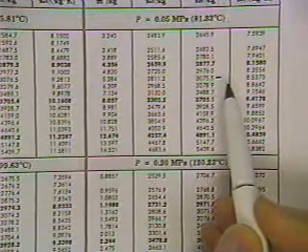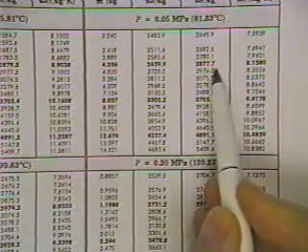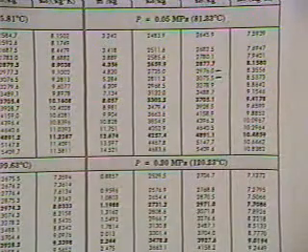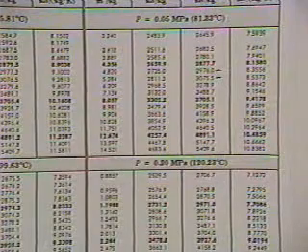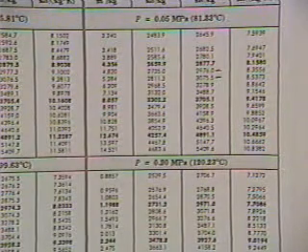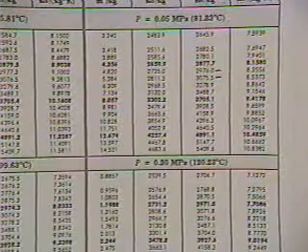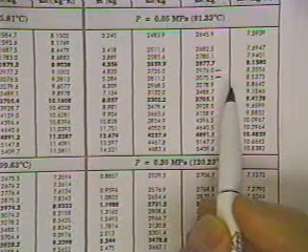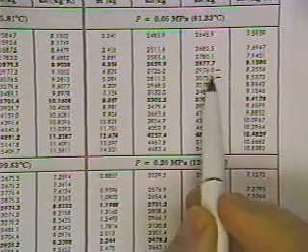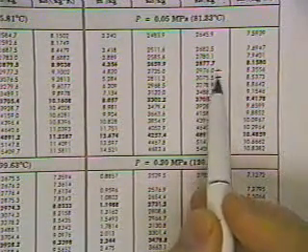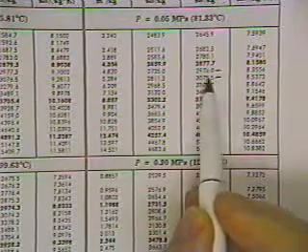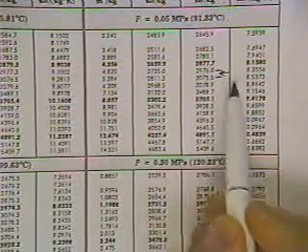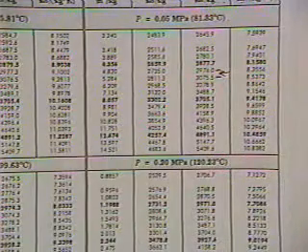so we are between a temperature of 300 degrees and a temperature of 250, and we'd expect that's where we'd start out, because our temperature doesn't drop too much as the flow goes through a nozzle. But this is an interpolation problem. We have an enthalpy of 3021.8, and the temperature is going to lie between 250 degrees centigrade and 300 degrees centigrade. And so in order to find the temperature, we've got to interpolate between those two values that are on the table.